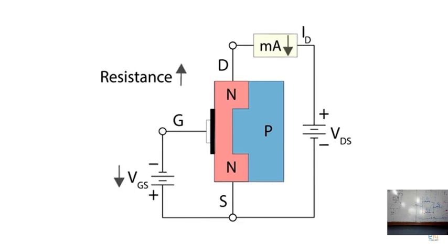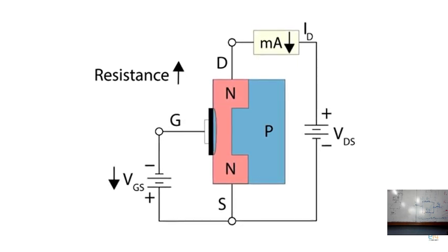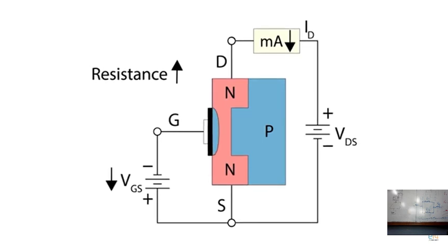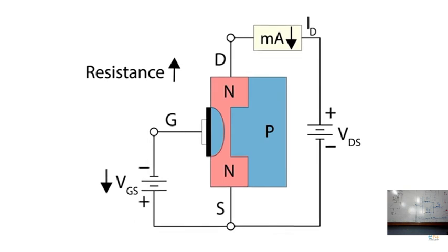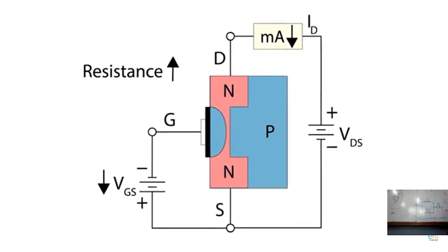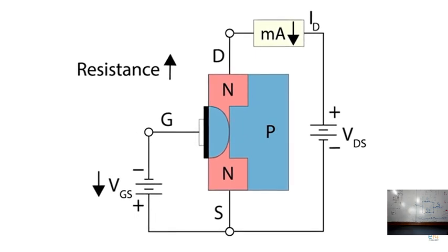When there is a voltage at the gate, and the gate is reverse-biased, the DMOSFET is operating in depletion mode. It behaves like a JFET. As the bias of the gate grows stronger, the depletion zone also grows. Proportionally, the channel is narrowed, increasing the resistance and restricting the flow of current through the channel between the source and drain.